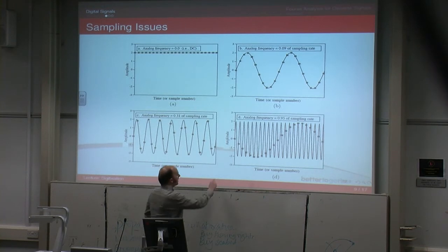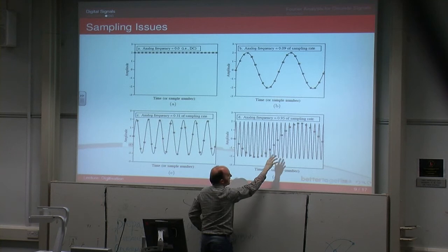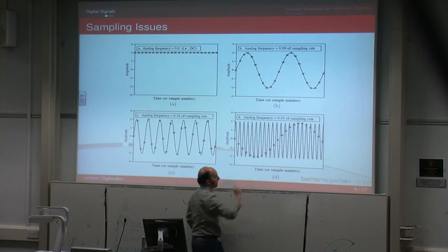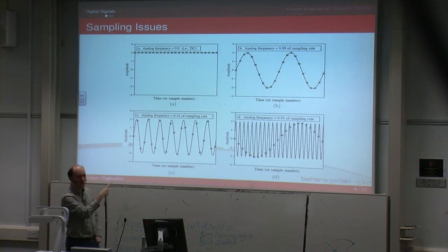You can see that with the same sampling rate, we've got a value. If you took away the sinusoid, you'd end up thinking, well, that's going to be a sinusoid of that frequency. That's wrong. It's not correct, and that's because this is aliased. That's what it means.